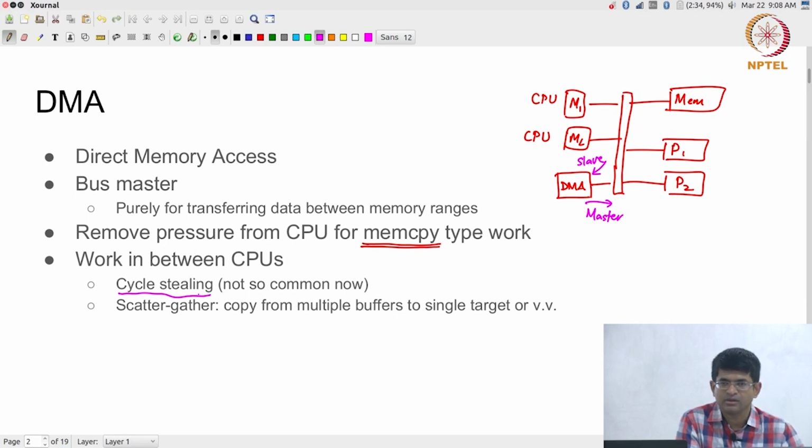Okay? Why? Because if you don't do that, then the CPU is going to get blocked until you have transferred all 1000 bytes, and you can't afford to do that, right? Then the CPU takes over, chugs along, does some work. The moment it releases the bus, it's no longer doing a memory operation. Because the request from the DMA was always high, it will get the next grant, again transfer some data, release it after a short while, and so on.